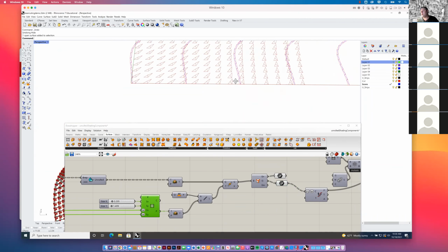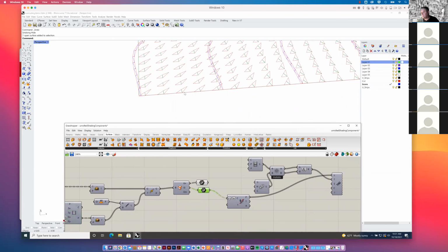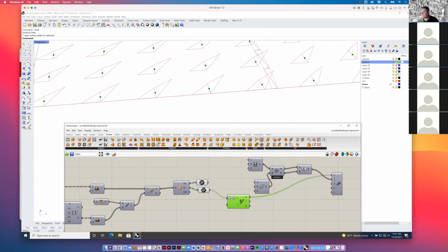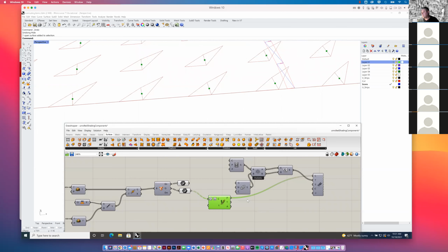And it's their orientation, which side is inside or outside, which side is up, becomes a real puzzle, unless you've thought about this. So what I've done over here is I've taken each of these score curves and I found a point along it, just by evaluating them at a t parameter, halfway along, I think. And then I use that as the position for a text tag.